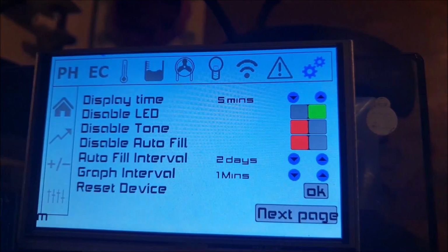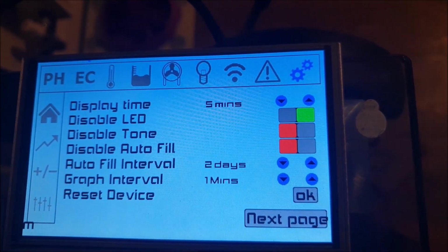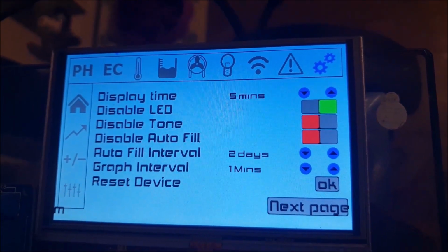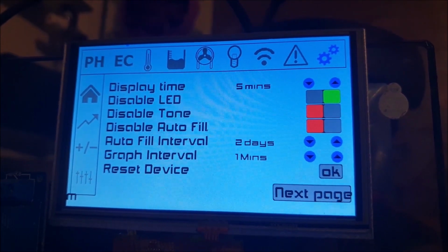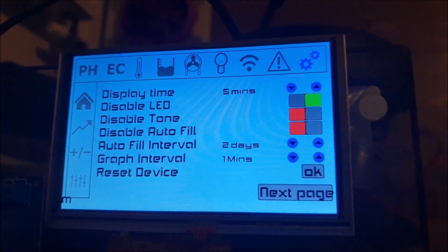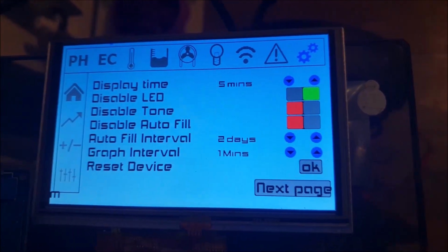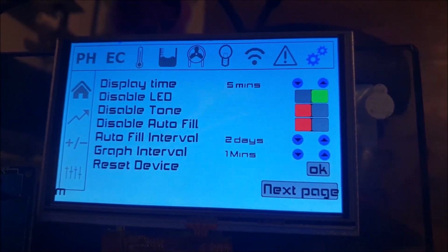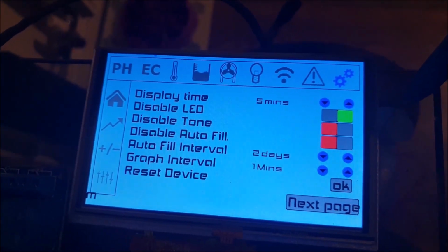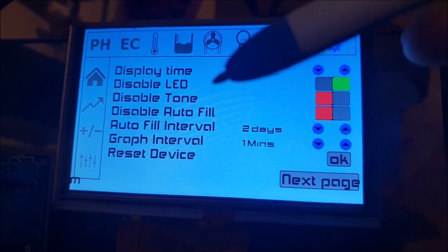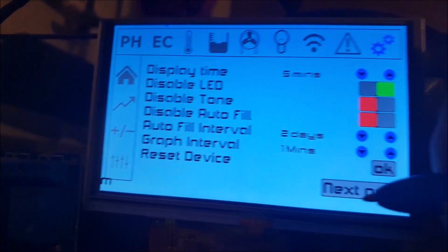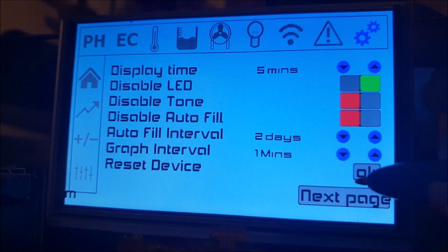So when it boots, by default an EEPROM block would equal 0 or 255, I've found that some come with either. But let's say you've bought a brand new Mega, it would either have 0 or 255 populated in all the EEPROM blocks, so you can guarantee that it wouldn't equal 101. So when it first boots, if the EEPROM block does not equal 101, it will save all the settings. So therefore, auto-populating EEPROM. Very nicely done.